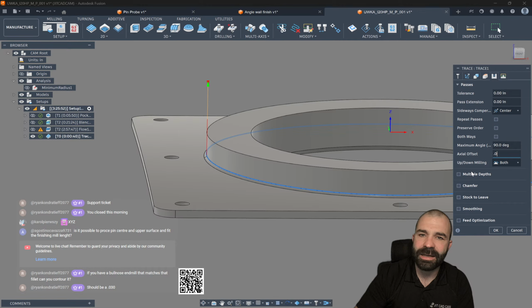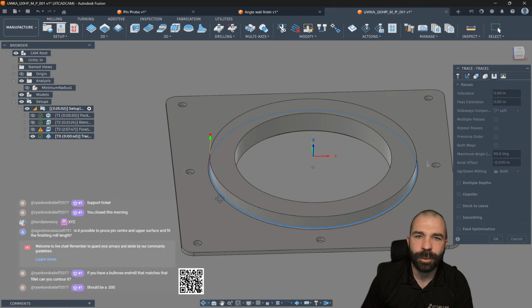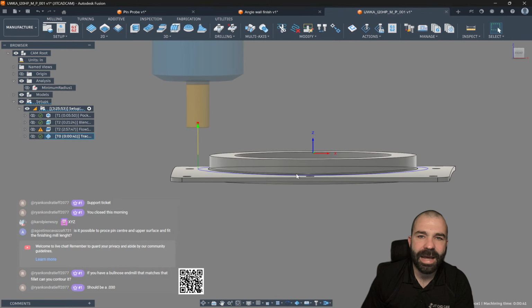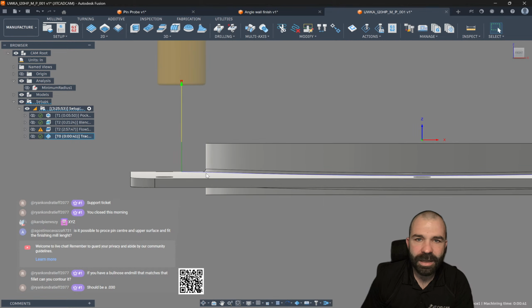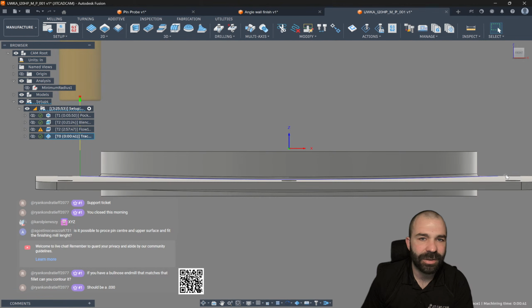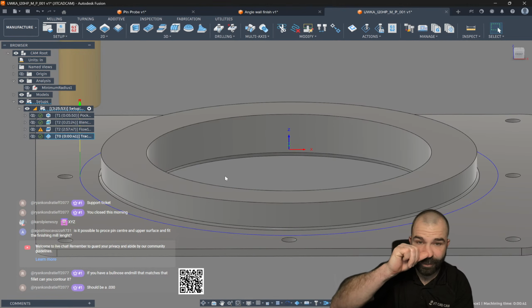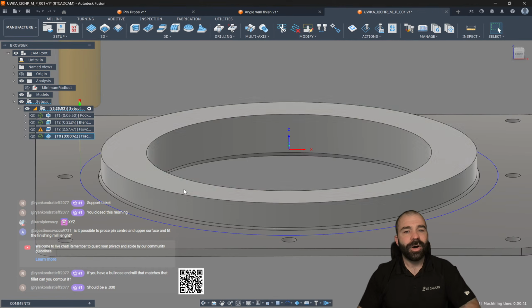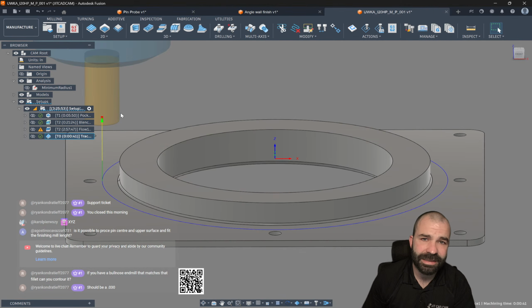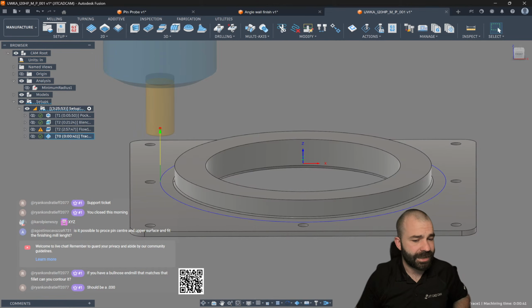So if I go in again, and we're going to say a negative offset down, and then I'm going to set my cutter comp to either left or right, depending on which way you prefer to machine. But just like that, I am now running around the part, and that blue line is going to dip and increase as it goes around, giving me more or less that fillet as well as wall finishing all in one shot. Now, again, if I went down to a 1/4 inch cutter, still had a 60 thou radius, it might suffice for your outcome and what it is that you're doing.